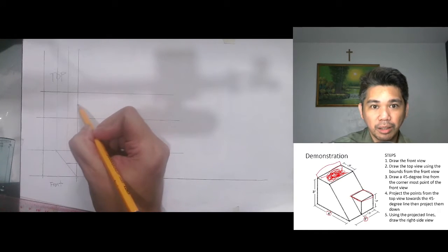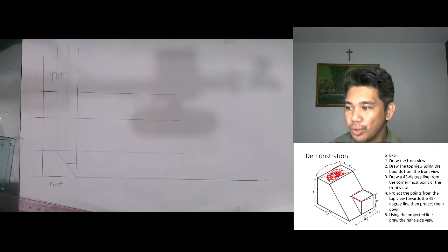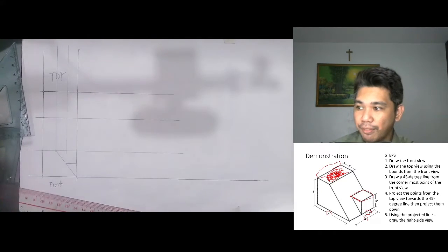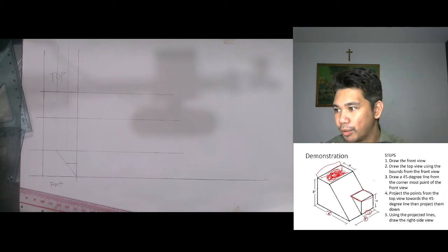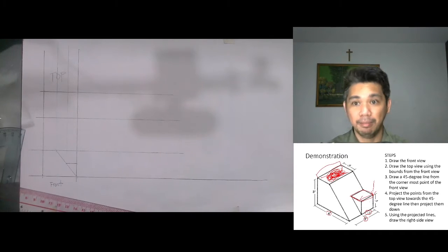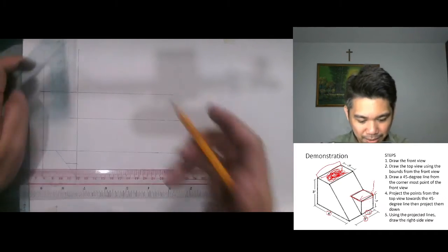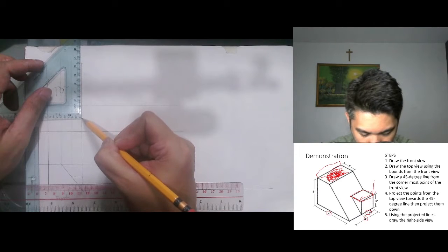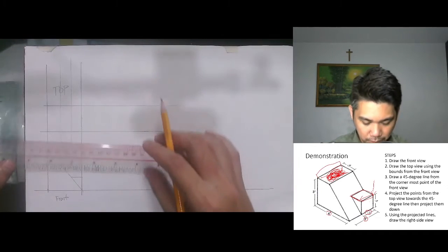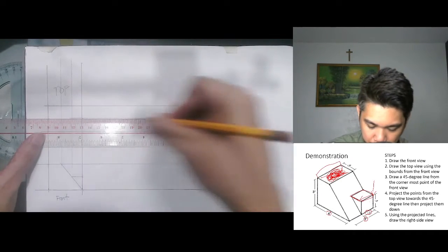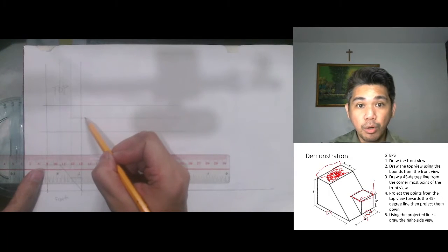We just have to determine its length. Where should it start? Since it's already placed that the length is 1.5, we only need to measure 1.5 from the tip. From this point, we will measure 1.5 and then it will form by itself already. So let me measure 1.5. So right about here. And then let me place a horizontal line.